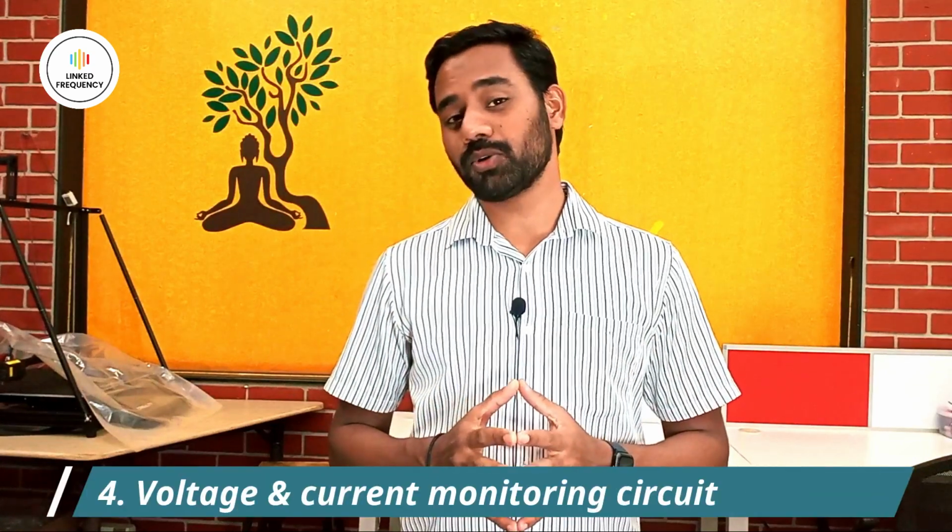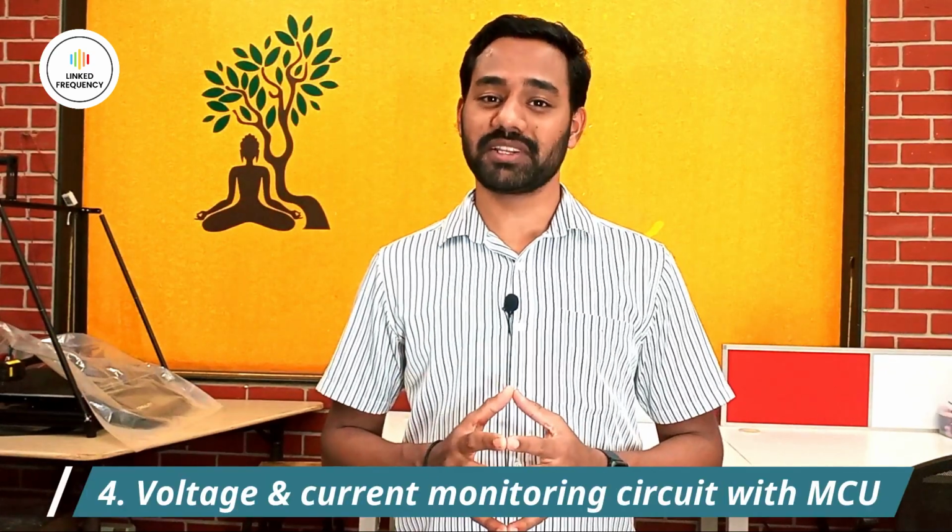Now it is time to talk about in-circuit voltage and current monitoring circuits with MCUs. It is very essential to monitor the voltage level and current flowing through the circuit in portable devices, because there is a need for power management with respect to the operation of the entire circuit. We can literally use a voltage divider circuit and a shunt resistor to monitor how much voltage level is left in the battery and also the amount of current flowing through the circuit, and take a decision based on that. However, there are some dedicated power monitoring ICs available in the industry, called fuel gauges.